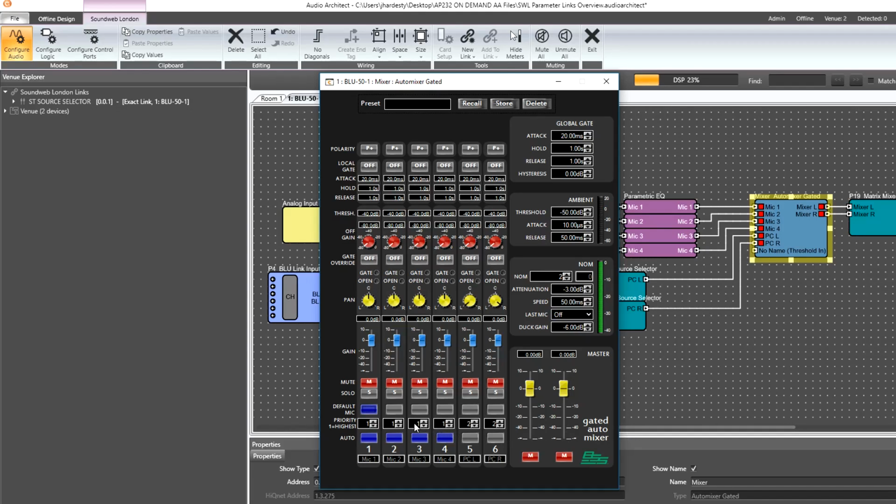However, as we test this out, we'll find we can turn on multiple default mics. We don't want multiple open microphones, otherwise that may cause more ambient noise to be reinforced in the system. Let's set it up to always have a single mic be the default. If another mic is selected as the default, then the previous control will be turned off. Click on New Link, select Radio, and we'll give it the name Default Mic. Carefully drag this onto the default mic control for each of the 4 microphones.